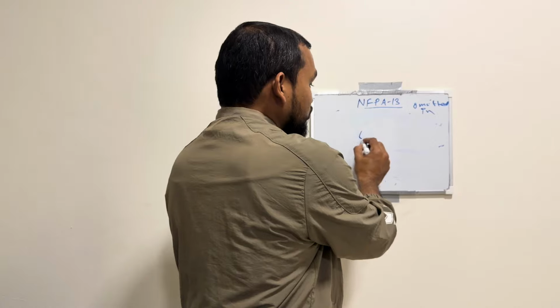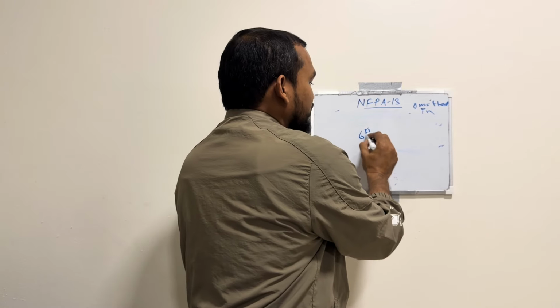Importantly, these assumptions do not apply to apartments, dormitories, or nursing homes. In this case we do not require a sprinkler. In a hospital we can omit the sprinkler if the closet area is less than 6 square feet. With a 6 square feet area, we can omit the sprinkler. In a hospital, if the distance from the sprinkler to the back wall or closet is within the maximum wall distance allowed by NFPA chapter 9, we can omit the sprinkler.